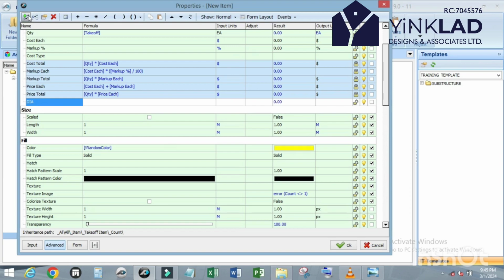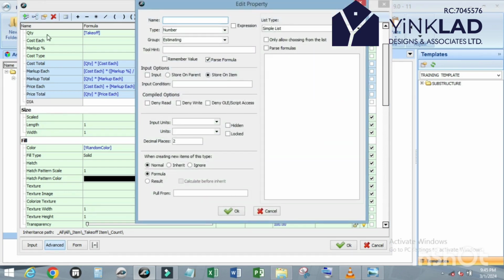So after diameter, bar weight. So bar weight of 16 mm is 1.579 approximately. Then next one of 20 mm is 2.467 approximately. Then for 22 mm, that is 2.985. Yeah.